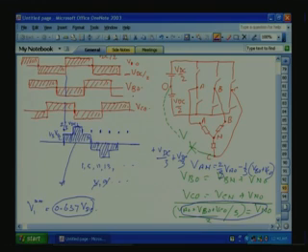So, the pole voltages are switched in a rectangular pulse with a 180 degree on and 180 degree off, with the magnitude equal to VDC by 2 and minus VDC by 2. If you do it pole voltages, the phase voltage will have a 6-step waveform like this.